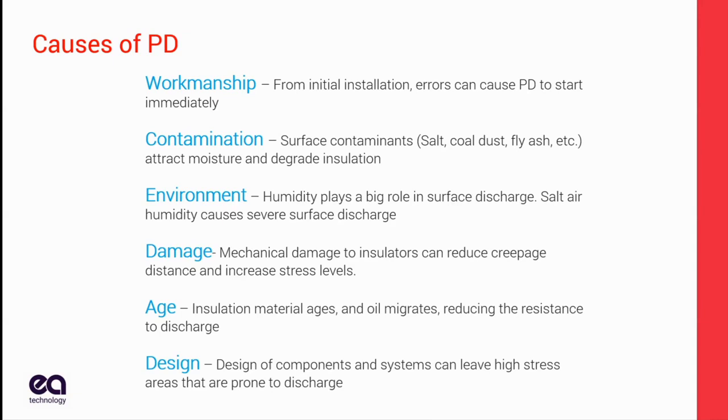Age. Some materials, not so much the solid state materials like XLPE, they don't age too much, but with PILC, the oil can migrate away from certain high spots in the cable, leading to PD. And then design. It doesn't happen very often, but you'll get components that are not designed well, or are so hard to install that they're never installed correctly. That's kind of halfway between workmanship and design, but if it's too hard to install, then you shouldn't be using it. So these all contribute to cause PD in the field.